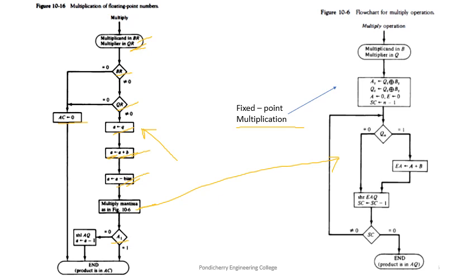This is termed normalization. Again, we have already talked about normalization. Normalization is making sure that the most significant bit position in the magnitude is equal to 1 instead of 0. We need a non-zero value in the most significant bit position to make use of the entire register size, to have the best possible accuracy. So here normalization is done. When a1 is 0, it is not normalized.